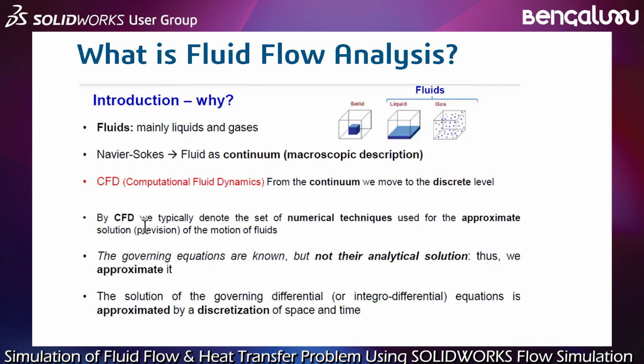So as I told you, the solution of the governing differential or integral differential equation is approximated by discretization of space and time. Discretization of space: if you are familiar with structural analysis, you have to mesh the part. Here as well, we have to mesh the fluid domain, okay? This is the discretization of the space. And of course, we have to discretize the time because we have to find the solution step by step. We cannot find the solution in one time step.